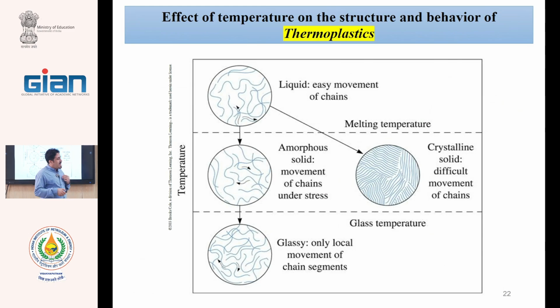Therefore, the performance of a gas separation membrane is very, very related to the temperature. In a liquid membrane, with an increase of temperature from 25 to 30, there is no change in flux, maybe 1%, 2%. But in gas separation, the temperature is very important.